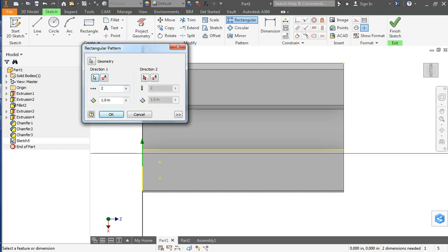Okay. Now I'm not going to say OK because I want to now take what I've got and turn it into an array. So I have kind of rows and columns. And so I'm going to choose a second direction. This one's going to be the horizontal line. And I'm going to go the other direction this time though. I'm going to fill all this. So I'm going to flip direction, and I'm going to add. Let's see how far 10 goes. Almost. Looks like I've got room for maybe one more. Let's go to 11. That looks pretty nice. Not dimensioned, I know, but it's kind of evenly filling up the space, and we're just going to go ahead and accept that. Okay, so there you go.